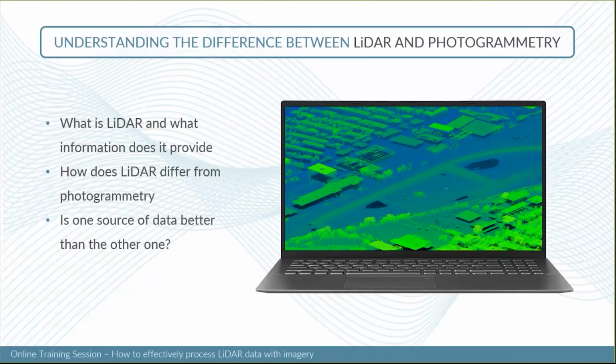And also, one big disadvantage of photogrammetry is that it's affected by occlusion. In order to generate an accurate 3D measurement, you need a minimum of two points of view. You need to see the point from two different perspectives. So occlusion could be a big factor, especially if you don't have the appropriate overlap. Then the occlusion could be much more important.